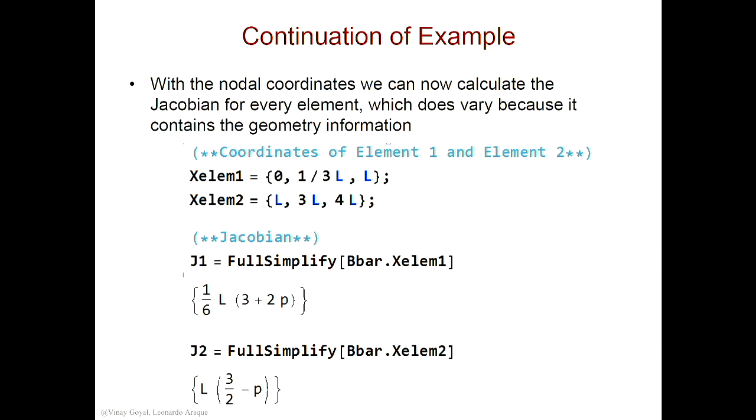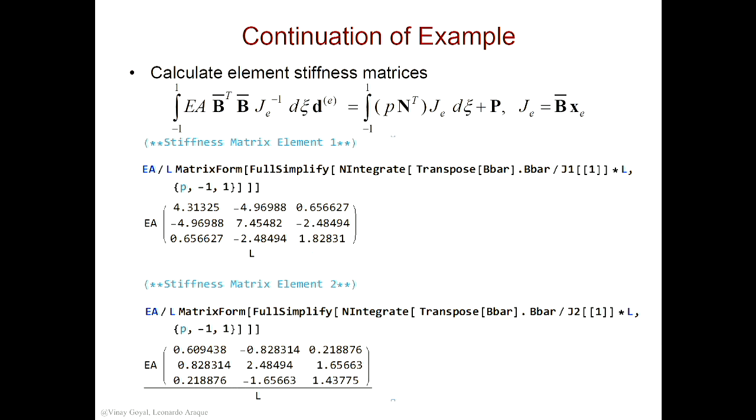Basically, I'm just selecting that from the list, extracting that number. But you can also write that. And then the integral goes from minus 1 to 1. Check this out. Does b bar depend on x? On the coordinates? No. This only depends on c, and it's the same for every single element. J1 is the only thing that depends on the coordinates.